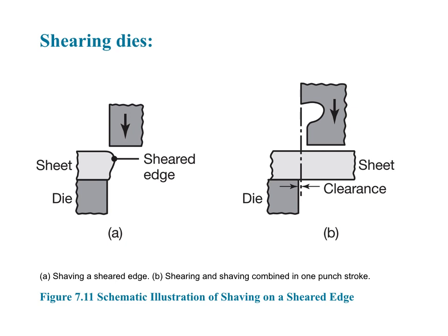Now, the quality of the shear produced influences the formability of the shear product. For thicker sheet, the clearance is kept higher. Controlling the clearance is important for obtaining good finish. Any extra material on the final product can be trimmed off the edge by a process called shaving. You can combine the shearing and shaving in one punch stroke, thus obtaining a better finish.